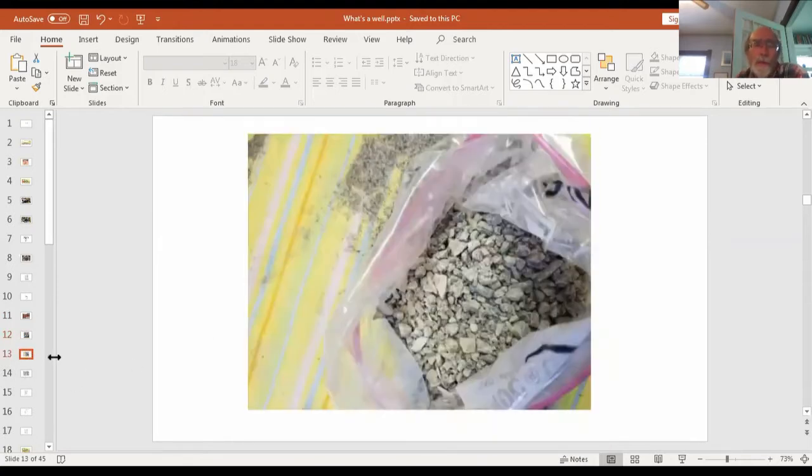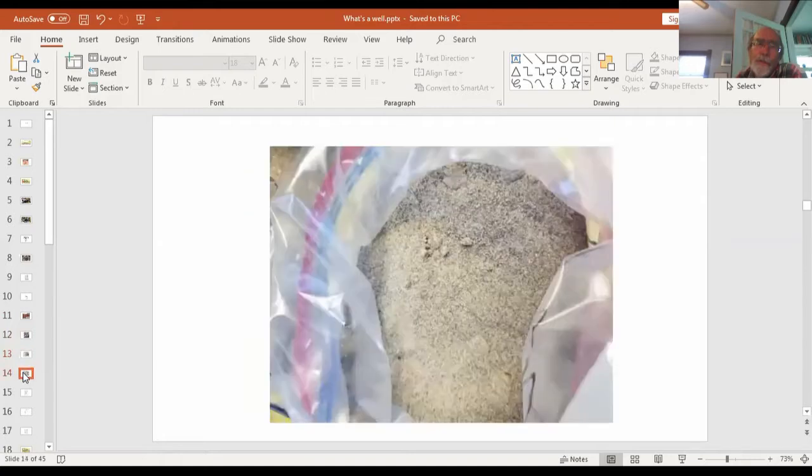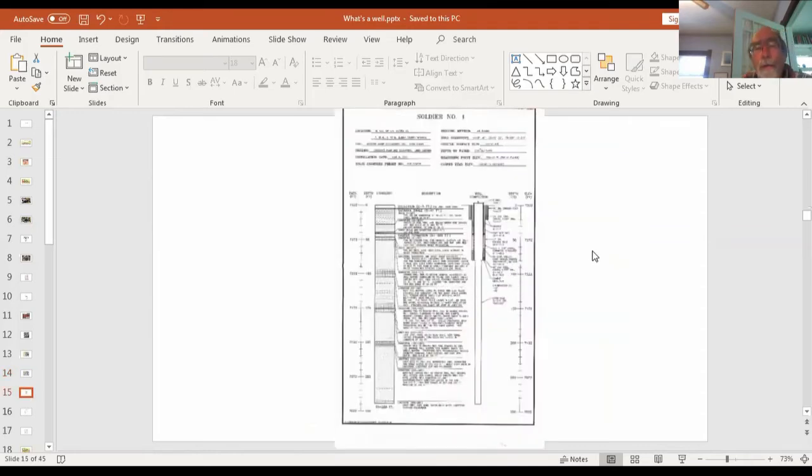And so here's a sample of drill cuttings, as they're called, that came up from a limestone layer. We ground it all up into this size chunks, and then we look at those and try to figure out what they are and what's down there, and then we can note accordingly. And for that well, here's one where we got into a sand that basically didn't break off in chunks, a few little chunks, but mostly it's just loose sand. Here's a place where you'd have trouble with the hole collapsing on you if you didn't put some kind of casing into it.